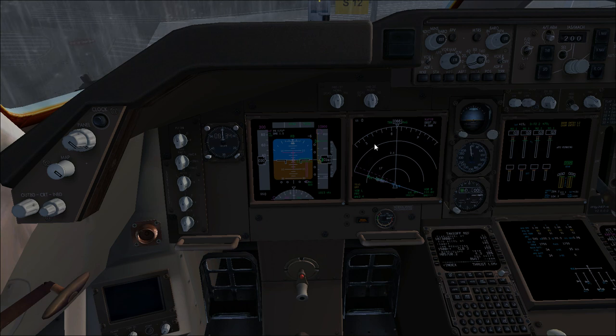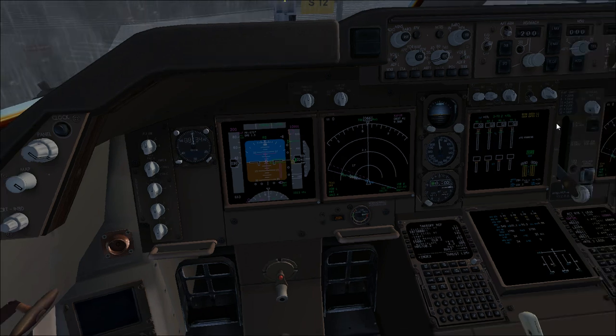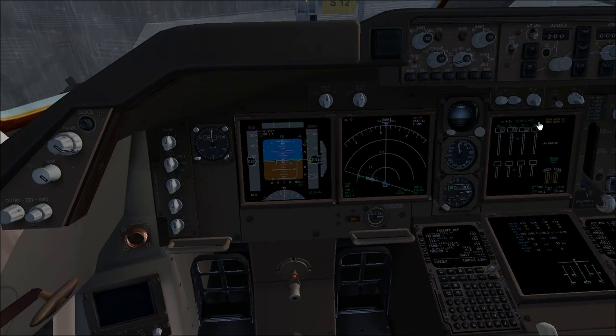If you modify one of them, you will have a failure. For example, if you select both the same source for both sides. For example, for the FO, air data computer is right, and we are in left. If we modify to the right, you will have source selector air data computer into the upper view. We will leave on the left one. The same goes for the flight director, source selector, flight director. While you select the center one is the auxiliary one or the standby one, so you will not receive any failure because the two sides of the aircraft are powered by different flight director computer or by different air data computers. Anyway, this completes our source select panel check.